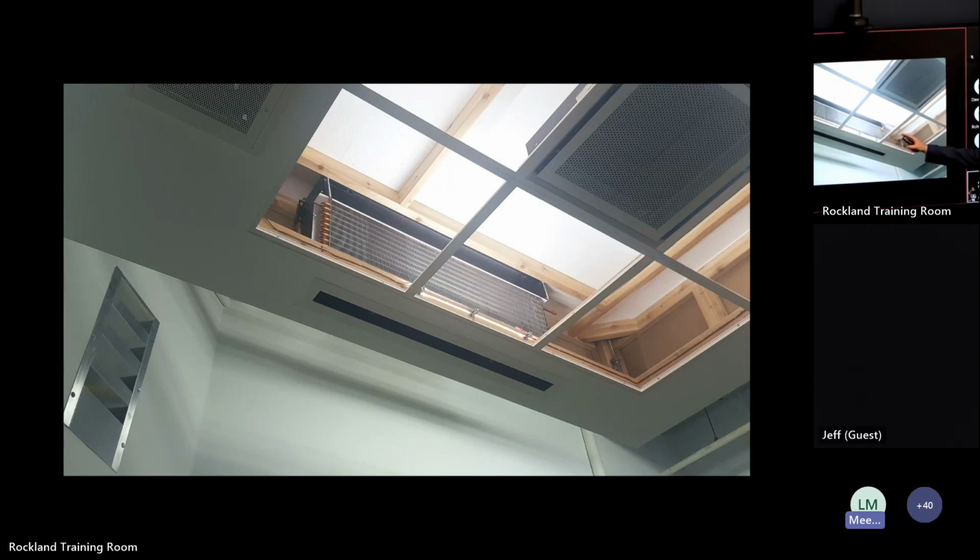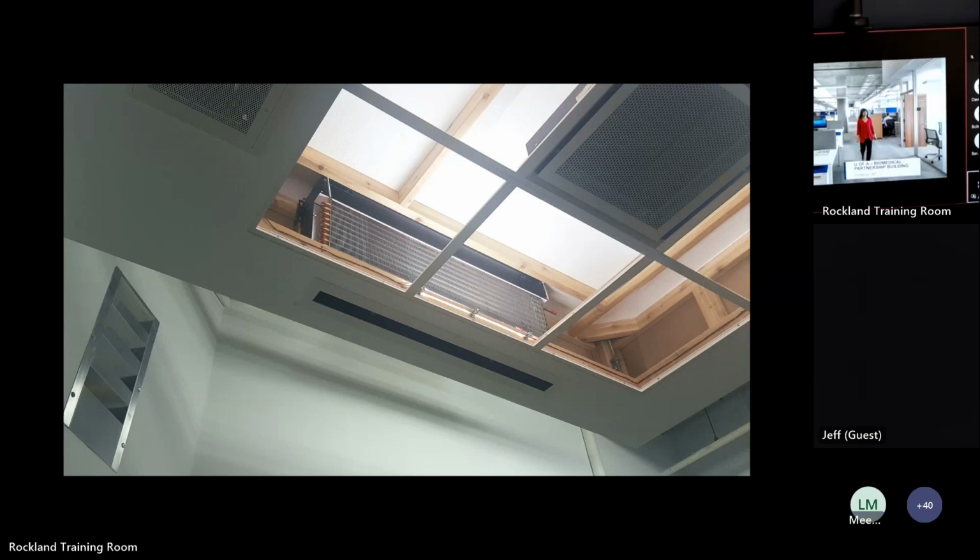Drain pan wise, if you were to design a wet coil design, the vertical unit is the only one you could put a drain pan on. There are horizontal recessed units, but that coil is horizontal as well, so you can't really put a drain pan in front of it because it would block all the induced air. Just something to keep in mind. Consider ceiling space for the vertical design, which is what's shown here.